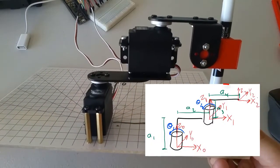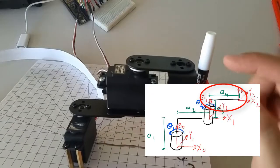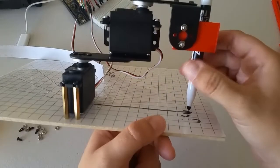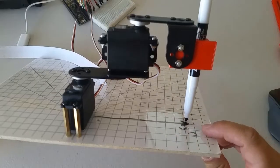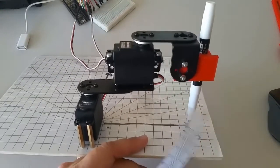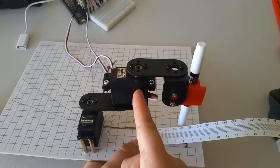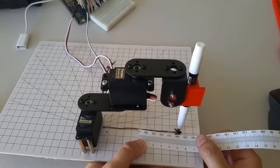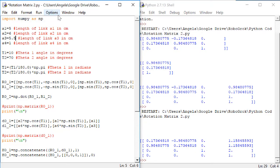And lastly, A4 is going to be all the way from the axis of revolution of this servo, this screw, over to the place where this marker is. Now this marker is tilted a tiny bit in mine, so I'm going to try and measure to the place where the marker tip is. So in other words, from the screw, if I would bring this down right there, to the marker tip is about 5 centimeters. So let's make A4 be 5.